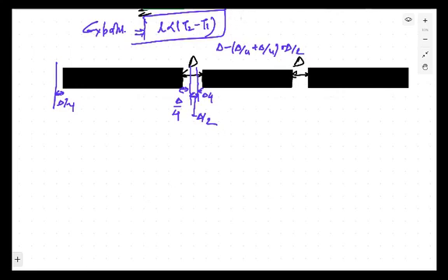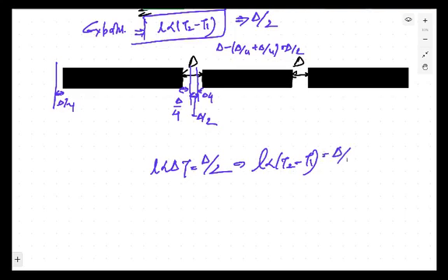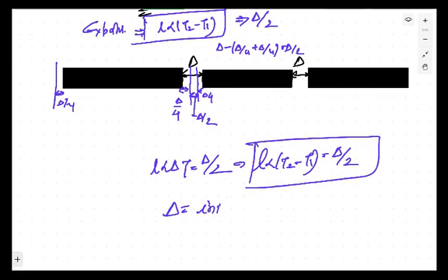Now the slab is expanded and the total expansion will be equal to delta by 2, because delta by 4 here and delta by 4 there make delta by 2. It means the full expansion of the slab that will be allowed is L alpha delta T, equal to delta by 2. Or you can say L alpha (T2 minus T1) is equal to delta by 2, where delta is the initial gap between the slabs. Fine. Otherwise, इससे ज़्यादा ऊपर allow नहीं कर सकते आप.